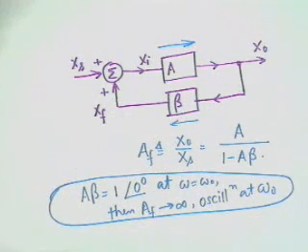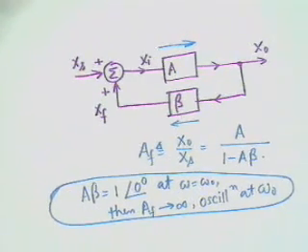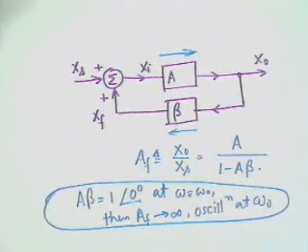Even if A beta is real, yes. Then it can be 1. What happens then? Nuisance. Since it is satisfied at all frequencies, if it is real, you get noise at the output, that is all. Nothing else. All frequencies are present, which means all frequencies mixed together will be simply noise.